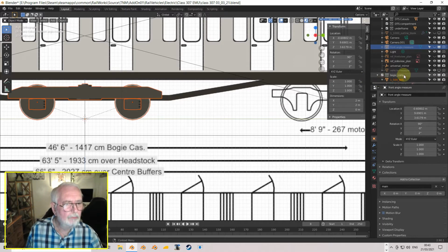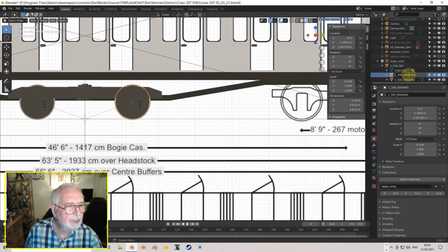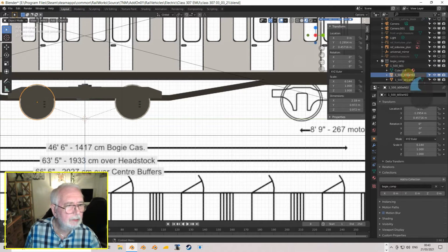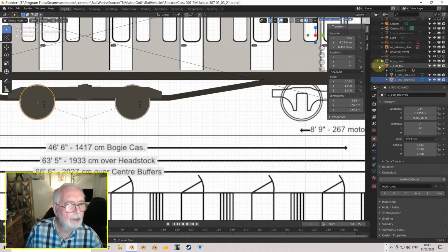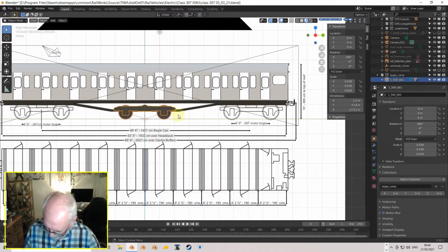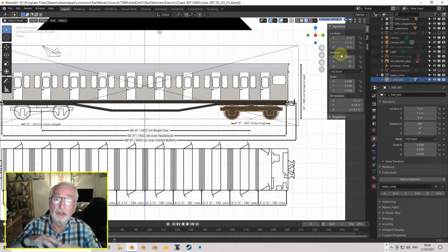Okay, so let's now rename this before we go any further. This should be bogie 01. Okay, we'll rename this as well, bogie 01 and bogie 01. There we go. So that's fine, that's bogie 1. Let's just select hierarchy, make sure we've got the children selected as well. Grab Y, let's bring it up here, and let's make it easy on ourselves. That's about right. Let's call that 7.2, so when we're making out the blueprints, it's not difficult to remember the actual Y offset.